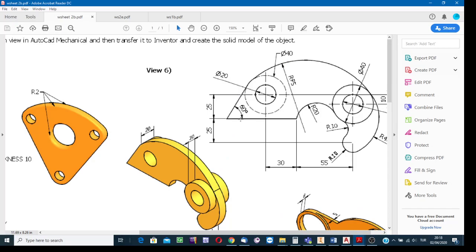I mean, do not input the inclination angle in any direction. Imagine as if you have such a reference line, horizontally oriented, passing through the tangent point, and relative to this horizontal line, calculate the inclination angle of the line as measured in the counterclockwise direction.